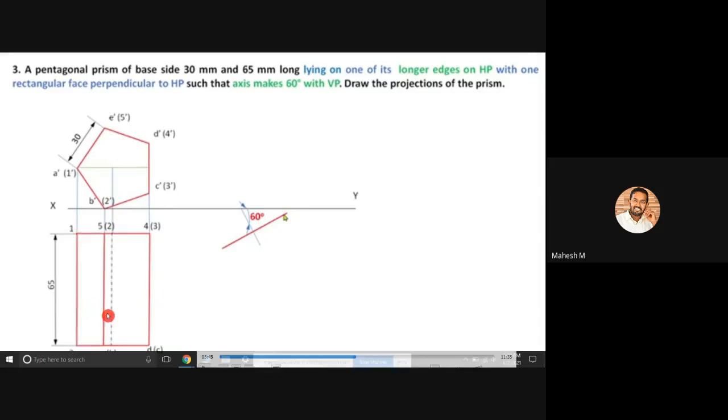So if you look here, it is 90 degrees. Similar to that, if you are creating a perpendicular line like this, it will not look perpendicular to you, because it is an inclined diagram. Even so, you can create a perpendicular like this: this is our base. Please consider this inclined line as a horizontal line. Then you have to use your protractor. The center point of your protractor should be here. Then you can mark the 90 degrees exactly at this place. Then you can connect these two points with the inclined line. Normally this inclined line is a perpendicular line. That means this inclined line has a 90 degree angle with the base.